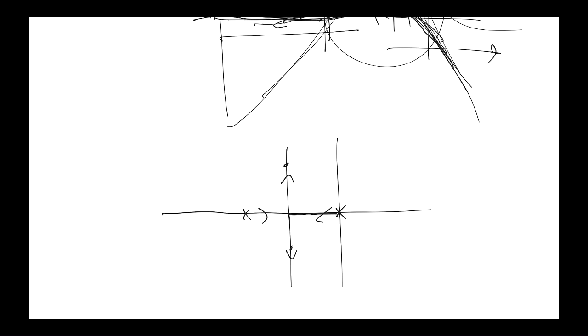And if you look at what would be happening to the complementary sensitivity function, for the low gains that put you here and here, you're getting complementary sensitivity functions that will just roll off without much peaking, right? And as we increase the gain further to move the poles like that, it's going to move across like that, so you're extending the bandwidth and making it faster. But as soon as you put the gain so that they're here, it starts peaking up again, right?